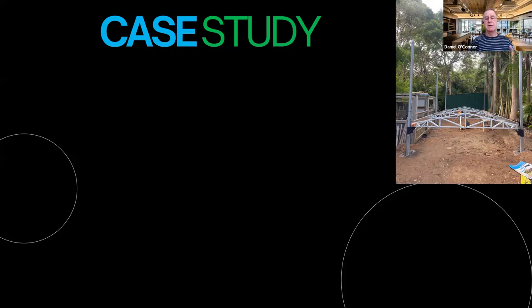Now, what David did is he engineered a sleeve that fits over the posts, and he then builds on those the trusses. He bolts the trusses to the sleeves. Once that's done, he can put the whole roof together on the ground. If he drops a bolt or a tech screw, he just picks it up. It's just that easy. There's no working from heights, nothing else. Once he's done that, he might put on solar panels, he might put on lighting, whatever he does.